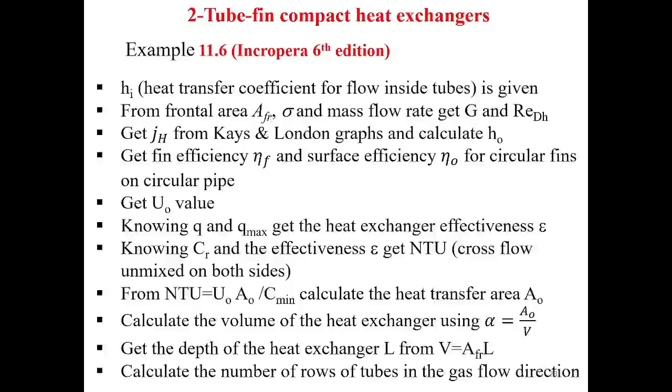The solved example is very clear, but it is very important in order to understand how to rate tube fin compact heat exchangers. There were two requirements for this example: the heat transfer coefficient H0 and the volume of the heat exchanger in order to fulfill certain duty.